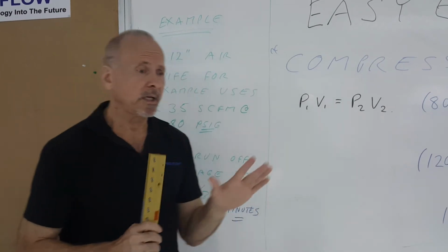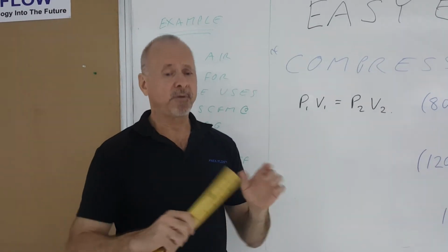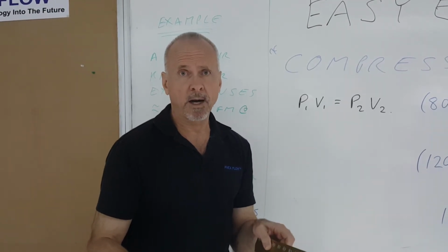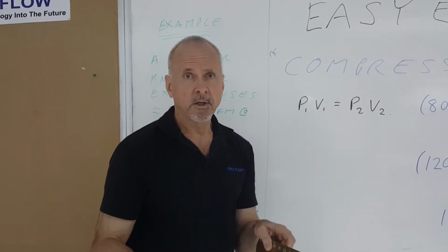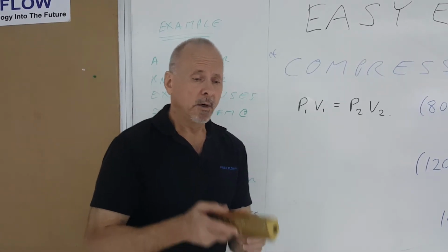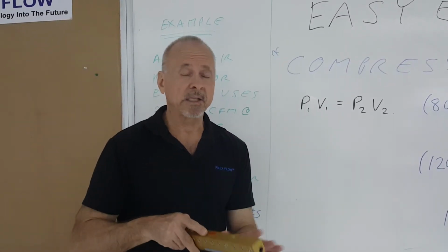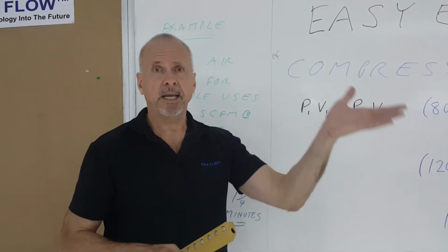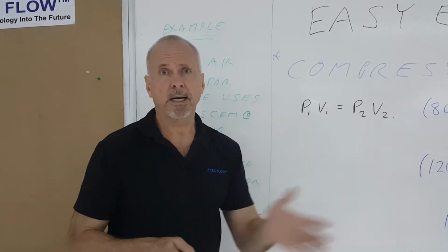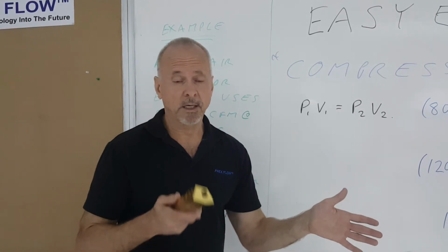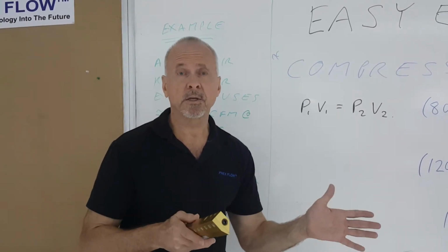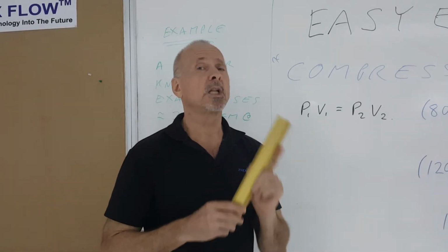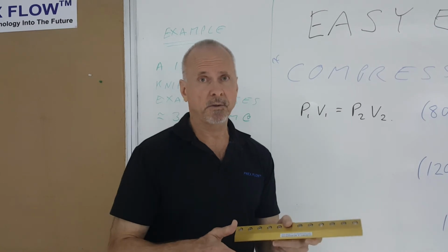Now, intuitively, recognize the implications of that. If you have an intermittent application for compressed air blow-off, you're not going to be using the energy all the time. When the air knife is off and the pressure falls below 80, that compressor will turn on and recharge that tank in the intermittent time that the air is not being consumed. So if you have an intermittent application, your overall energy consumption is going to be a lot less than if it's used continuously.